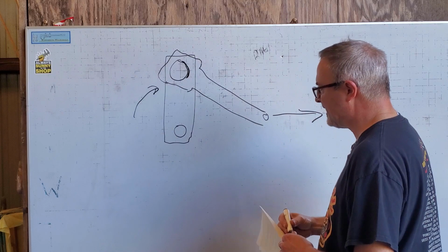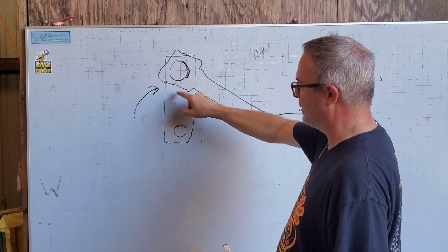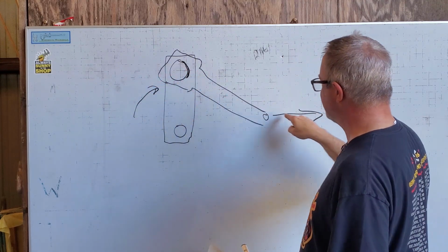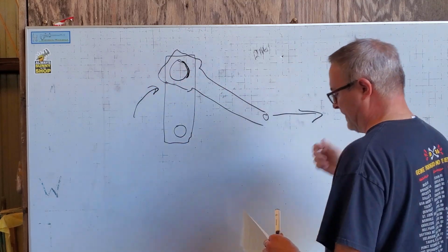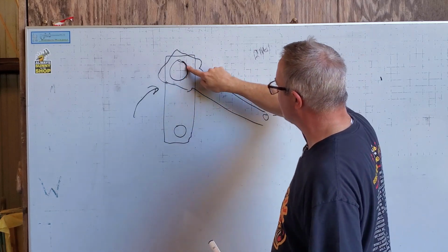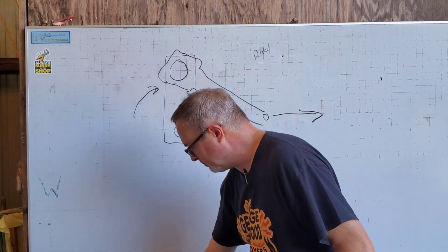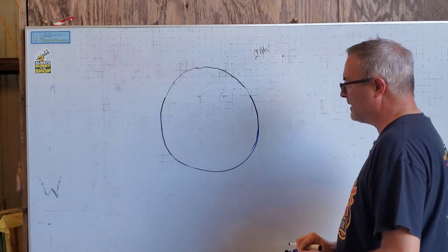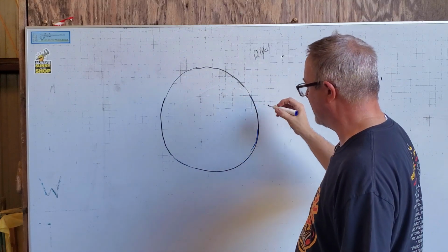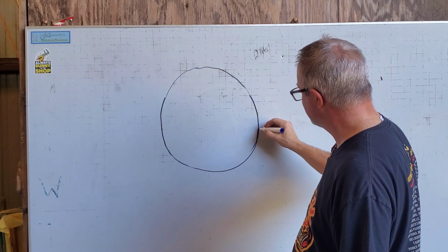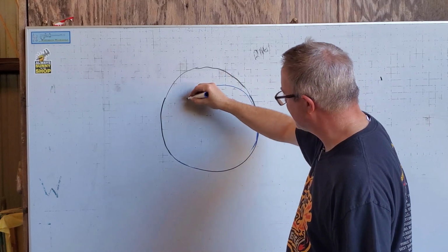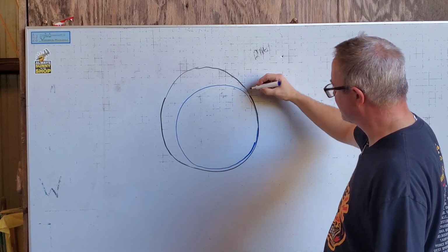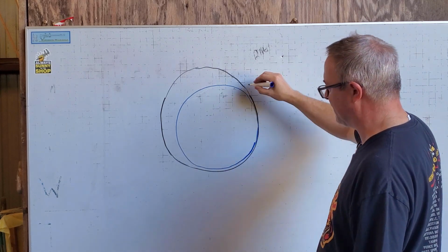Now, as soon as we pass front dead center, or let's say a 90-degree crank position, now this piston is pretty much at its maximum velocity. So it's going to cause this to swap sides. And if I were to blow this up, if we look at a big blow up of the inside bore of the connecting rod, the crank pin with its minute clearance, I'm going to greatly exaggerate the clearance, is pushing against the connecting rod. And so it's squeezing the oil film on this side down to nothing.